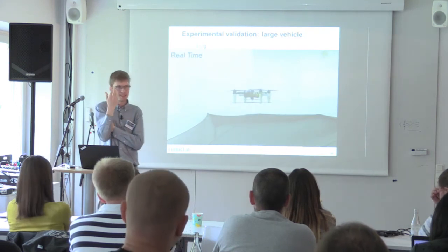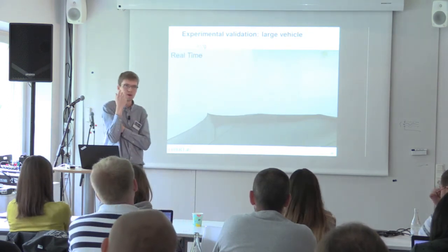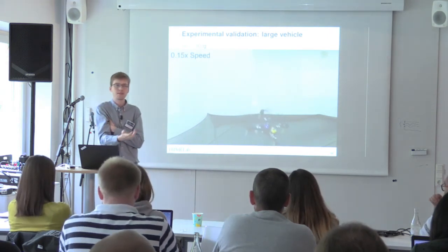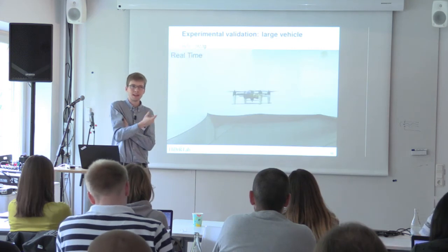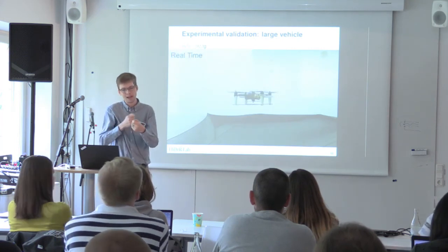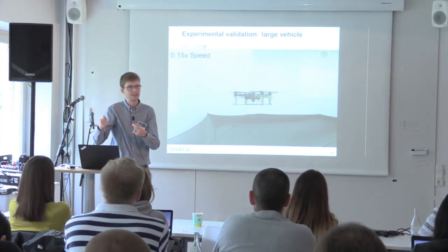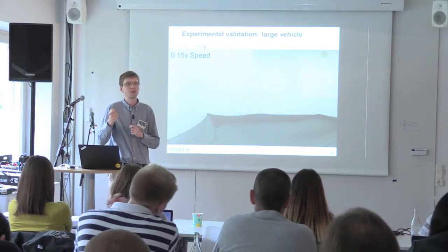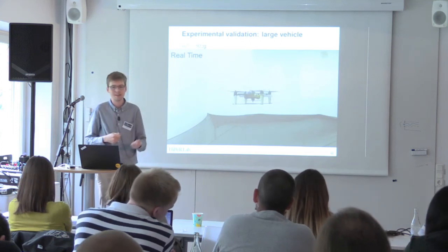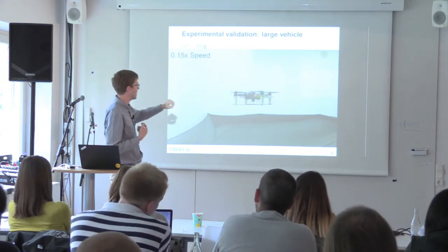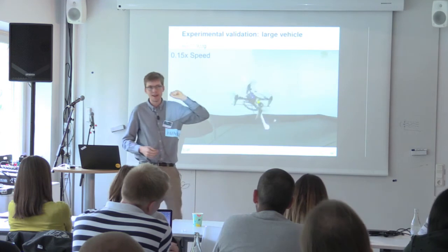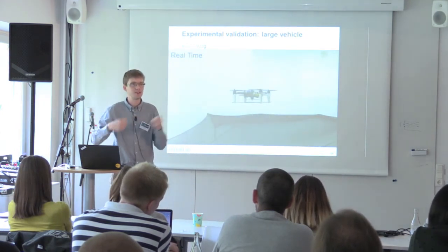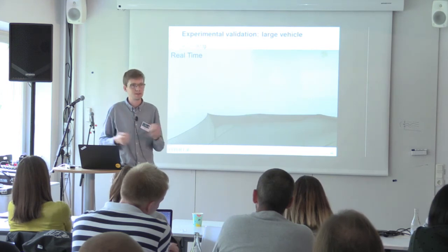But the concept in the background is similar for both. When you have this rotation, if you have angular momentum, you can exploit the existence of this angular momentum to modify the dynamics to give you different ways that your inputs, your actuation affects the dynamics. And having the flywheel gives you some more degrees of freedom in the controller. So you can imagine that, let's say I have this vehicle and one of my actuators fails. There might be an ideal speed at which to rotate the flywheel after the actuator has failed to make the controller as easy as possible.